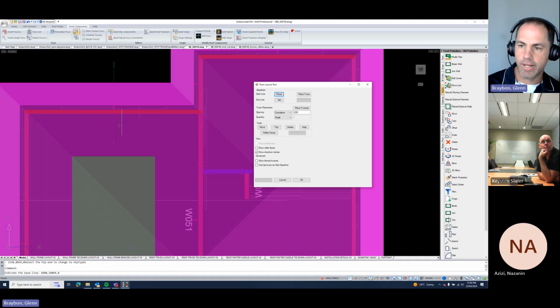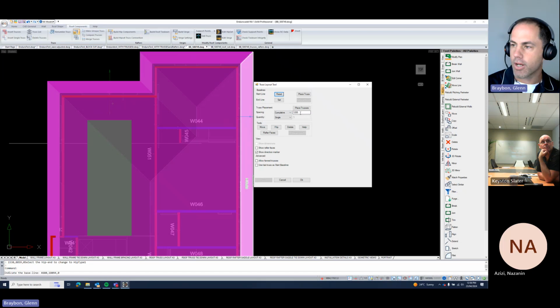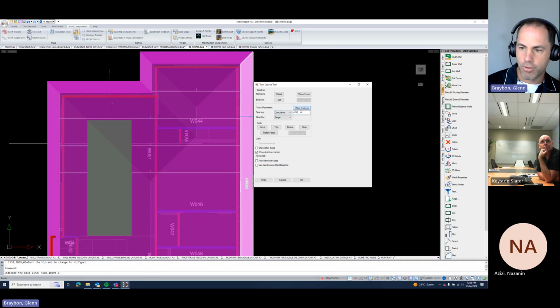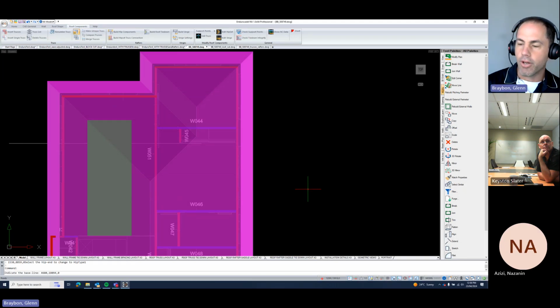You can see here it's a bit hard to read. I'm going to try and get that a bit better. We've got a plus and a minus. Minus is on this side. It's hidden in the eave, so I'll just go minus 40 for a truss. And then we'll go 1160 for a truss. And then it's going to put them in at 1200. So that command's no different.